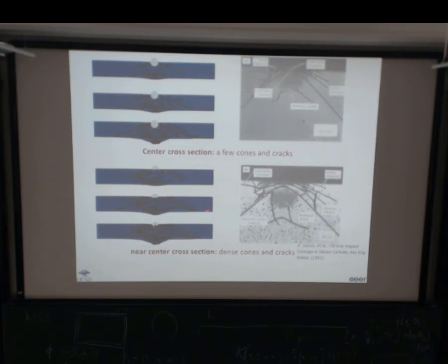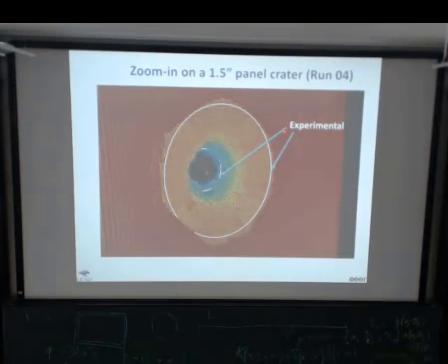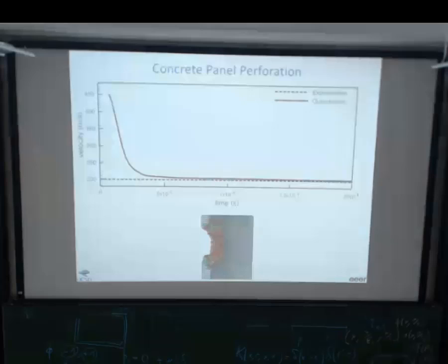Comparison with some crack branching, but this is damage mechanics. I'm not using fracture. Fracture is just used to construct the damage law. Everything here is computed by damage mechanics obtained from the microstructure fracture mechanics calculation, right? And so this is the level of detail that we can get through this kind of computation. We compare the damage zone on the exit side and entrance side to experiment, and as you can see, they agree quite well.